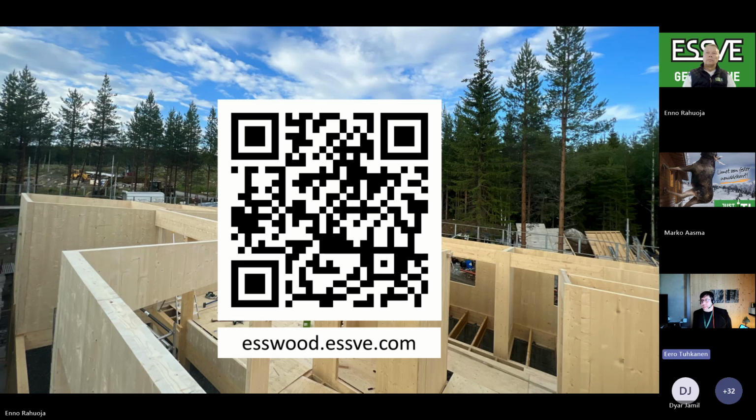and I think the screw can have a benefit here, because if the temperature rises a little bit in the screw, it doesn't affect the withdrawal strength too much. But the glued-in rod, the glue was also heated up and lost the load carrying capacity. So here I think the screw connection can have much more place. Yeah, but it's better when it's hidden. Yeah. Thank you.